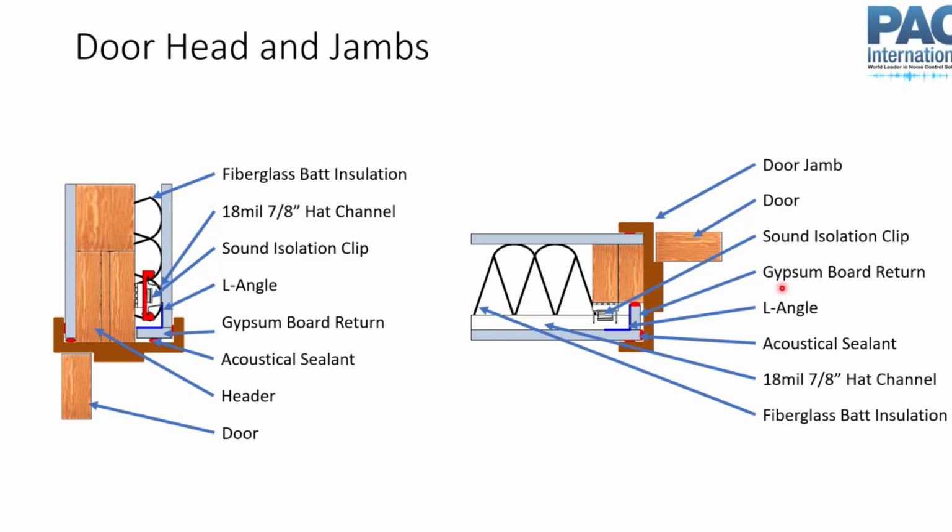This also comes up in office spaces, recording studios, things like that, where maybe we have an STC rated door. And so we have a higher performing door. So we need to make sure that at least for our wall, we're not creating structural connections across this and that we're sealing this all up. Now we obviously have the door or window, head and jamb that could be a structural path through here, but we're just going to kind of ignore that and hope that the door or window was tested with the door frame and that frame is designed such that it provides decent sound isolation across it.